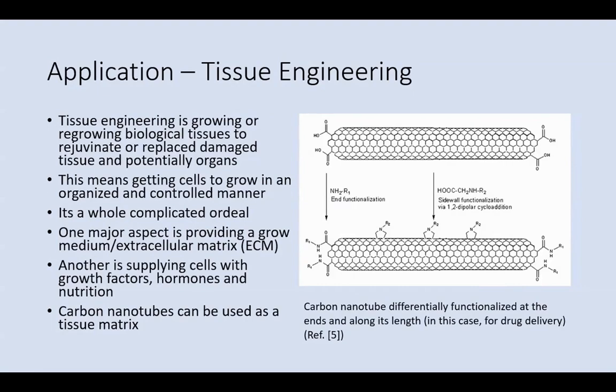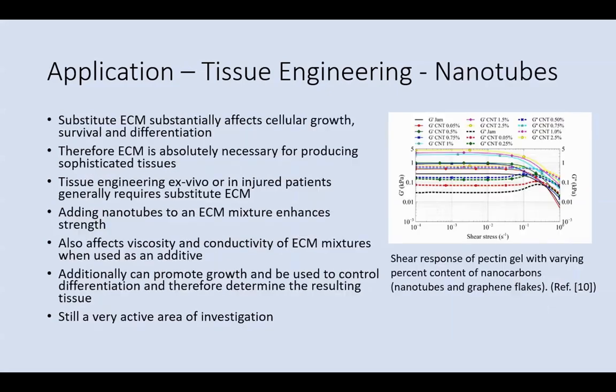So the result of this arc discharge process is a soot that coats the entire chamber, and that soot contains a number of compounds, nanotubes among them, but also a large quantity of graphene flakes and other undesirable carbon products, which is why we call it soot. So in order to get pure nanotubes, some purification is required, and there are a variety of methods available, including boiling the soot in acid, microfiltration, chromatography, usually in combination with more filtration, and thermal oxidation of the impurities, essentially burning off anything that isn't nanotubes.